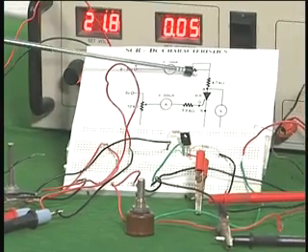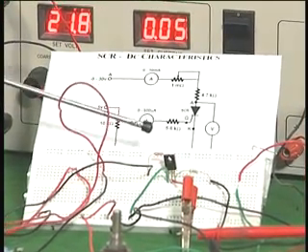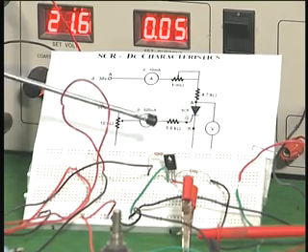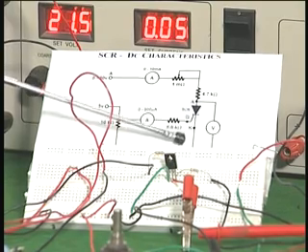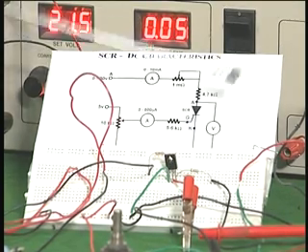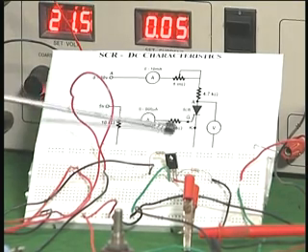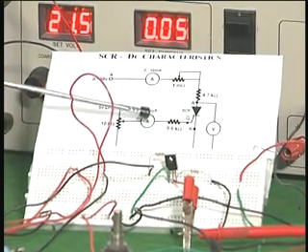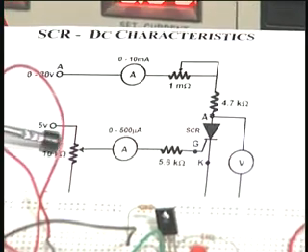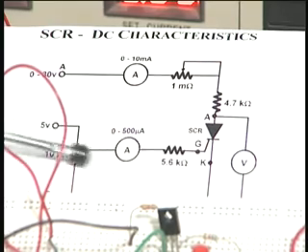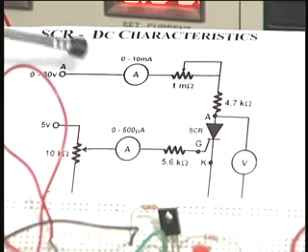Now let us go back to the circuit, and you have another 4.7 K resistor, and then this is the SCR, the C106 TO-225 package that is here, and then the gate and the cathode are connected to ground, and there is a voltmeter. I have a voltmeter connected there, and at the gate I have connected some 5.6 kilo ohms and a small 0 to 500 microampere ammeter, and there is a 5 volt potentiometer with 5 volts applied, which can vary the voltage, and thereby I can change the current. So it is exactly the same as the one which I explained to you.